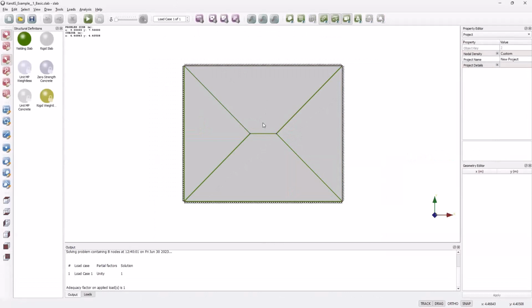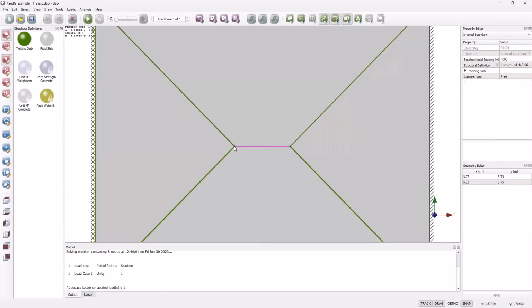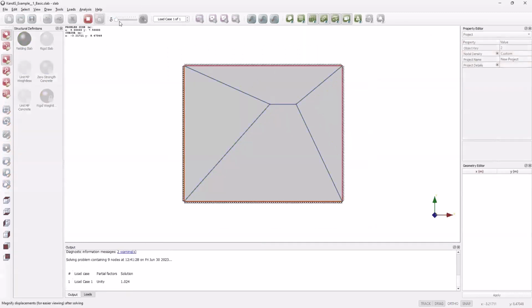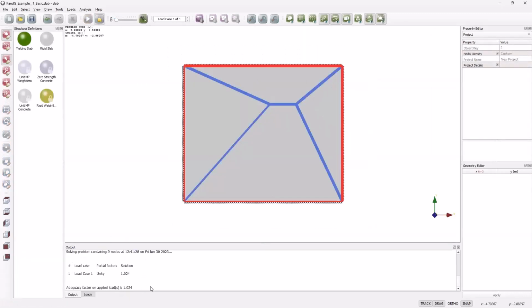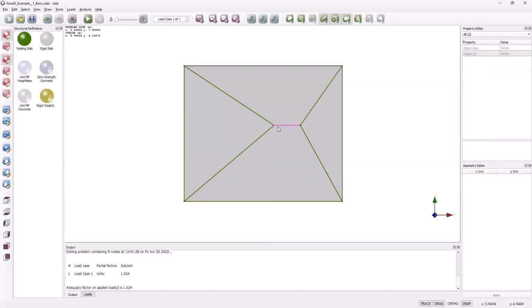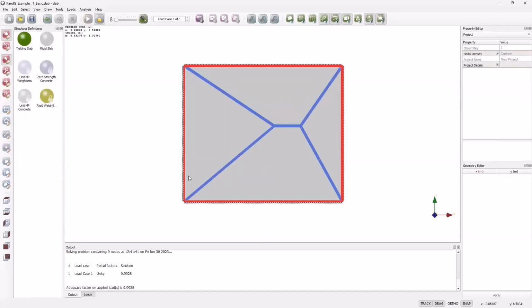So if I just unlock here, I can quickly just select that part of the structure, solve again, and we can see here, actually the adequacy factor has gone up. So it's a little bit higher strength with that one, but I can also move it down here and solve again, and it's just below 1. So from this, it's clear that if we more closely capture the true failure mechanism, the required moment capacity is above that original 37 kilonewton meters per meter that we found initially.